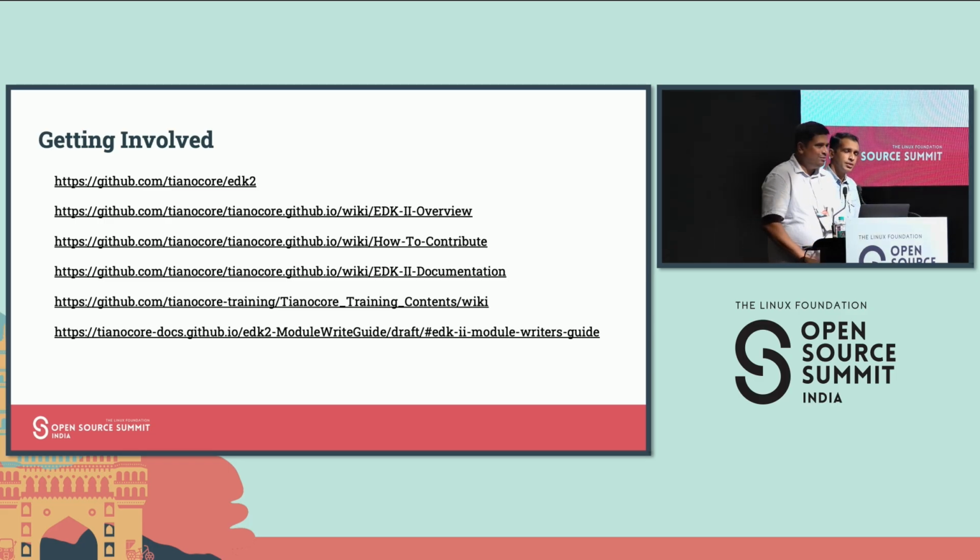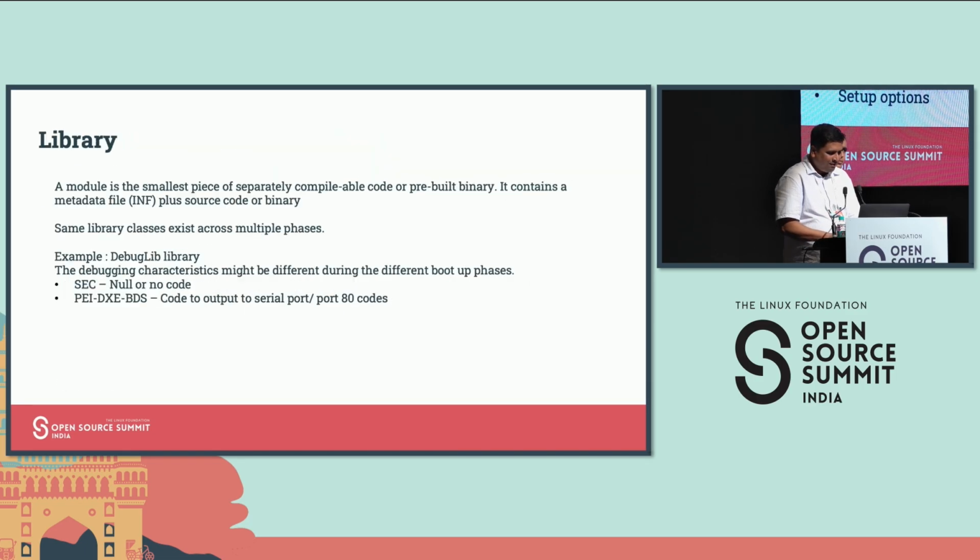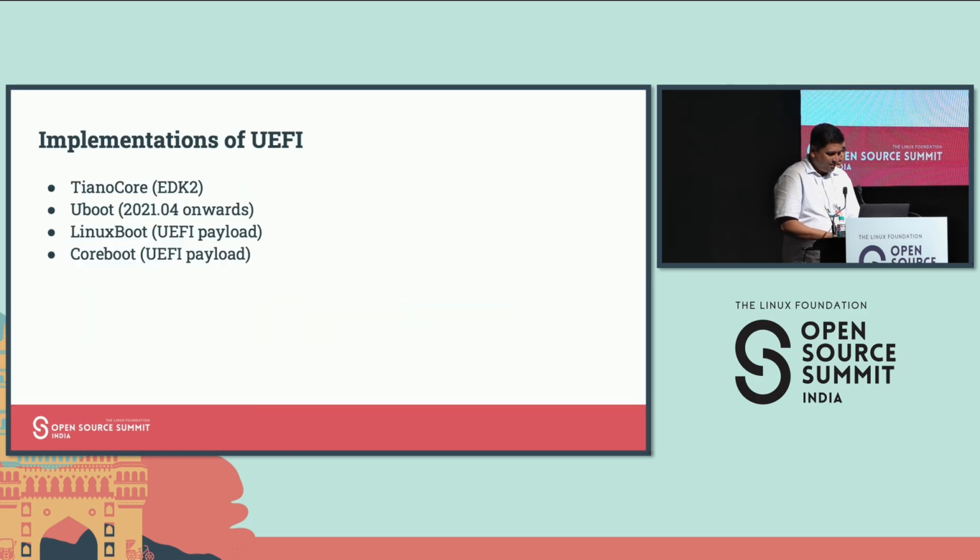Generally, embedded Linux doesn't have BIOS. U-Boot will follow the UEFI specification, but it is not looking for the same phases as BIOS, because in embedded Linux we don't have BIOS and we have memory constraints and all kinds of things.